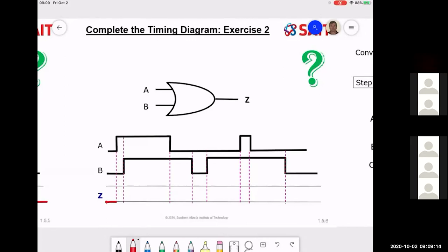William, okay. So I'm up to this first transition line. Will I be high or low after this transition line? Well, I'm going to say low. Low. So this is an OR. After this first transition line, A will be a 1, B is a 0. 1 or 0 should be a 1. So the output is going to be a 1.